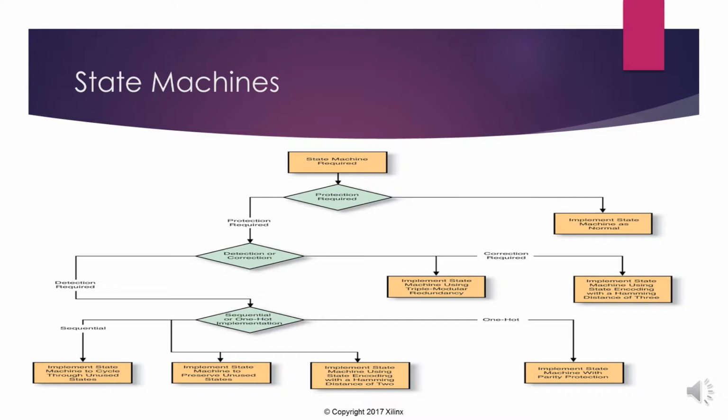Now again, that will change the functionality of the circuit, but that can be mitigated at the higher level because the state machine's terminated early. We can also get the state machine to preserve the unused states such that we take specific action in the unused states. Now, because there's no path into or out of that unused state, for instance in this example, we would need to maintain and use synthesis constraints to actually stop the synthesis tool from optimizing those out.